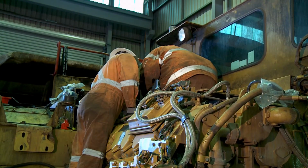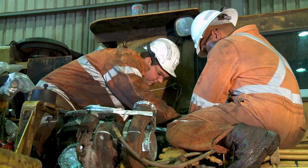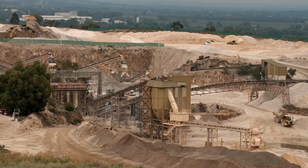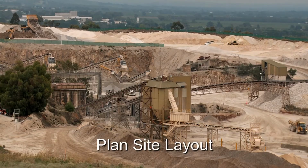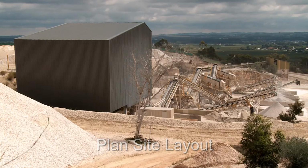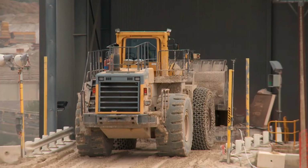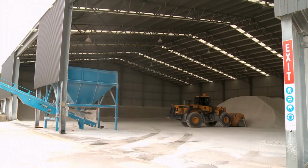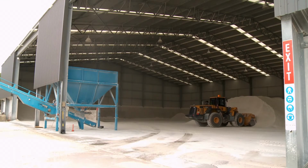Maintenance of filters and ventilation systems is crucial to the effectiveness of these control measures. Plan site layout to isolate excessive dust areas. Contain crushers and other processing plant with walls, sheds, and other barriers.